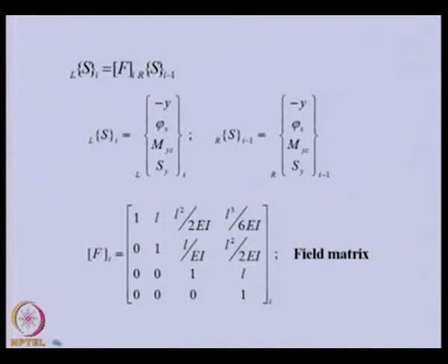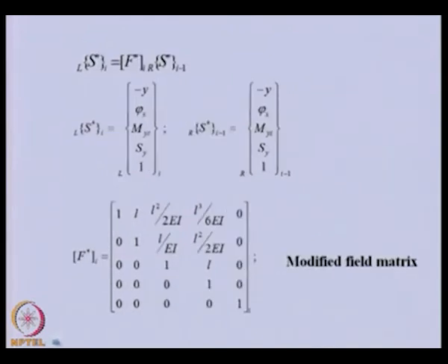If we have external force, then as we did in the torsional vibration case, we need to modify this field matrix by adding one identity at the lower position. So, basically we are adding 1 equal to 1. You can see this field matrix has all 0 added except the diagonal term, and here also 0. So, again if we substitute this here and this state vector here, if we expand the last equation,